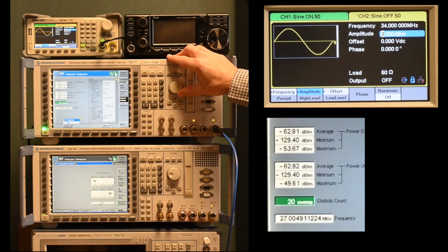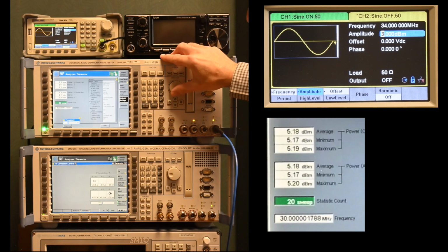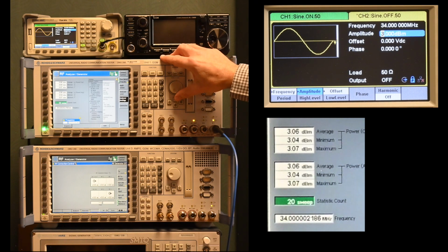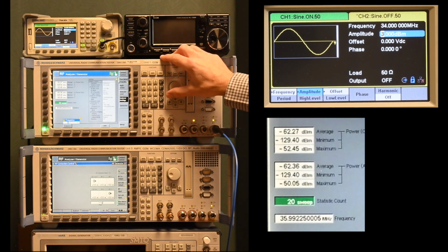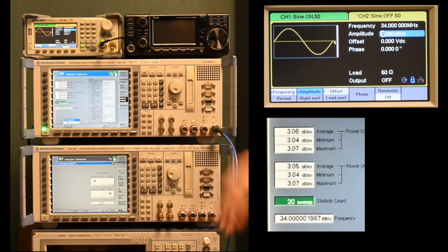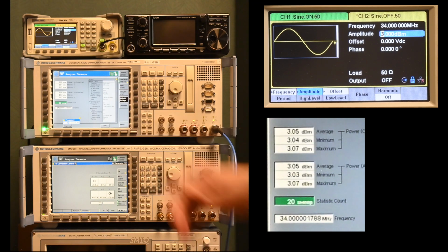So basically, 28, almost nothing at all, 29, 30, and we nicely see here the 5.80 dB. It's even slightly more than the 5 dB that I set there. Then again, nothing at all, nothing, nothing. And at 34 again, we see our 3 dB coming in. So that basically means that this is working fine. It's picking up the two different signals at the frequencies where these tones are present. And this is how the frequency selective menu works.